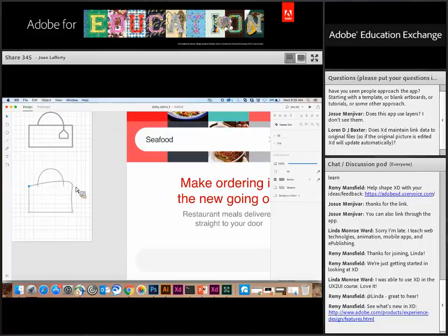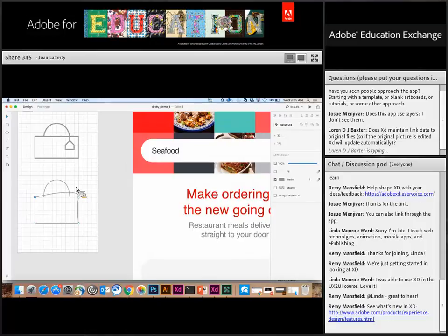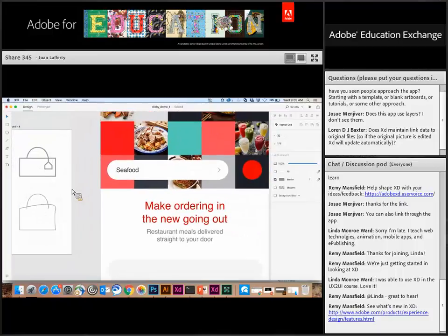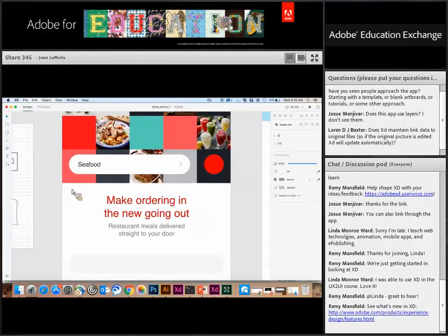And so those changes might come from Photoshop or Illustrator even. So if you have, say, 5 images in your library that are used in your XD file, somebody might change that library in Photoshop, and you'll automatically get the updates inside XD. So if you know that assets are going to be changing, you'll want to be sure to use a Creative Cloud library there. In this particular workflow, it's just a local workflow where we're embedding the images in the file. So if something changes, it won't change in your design.